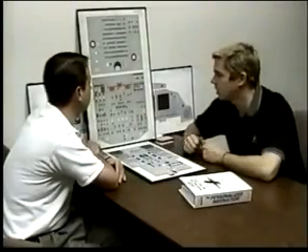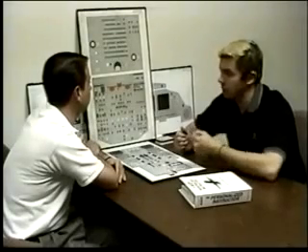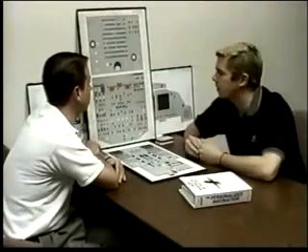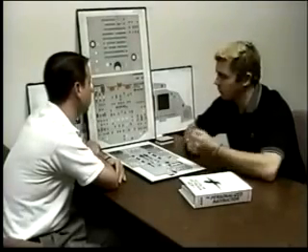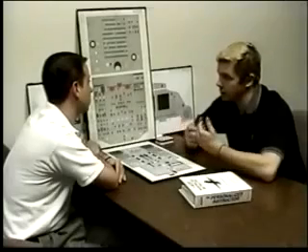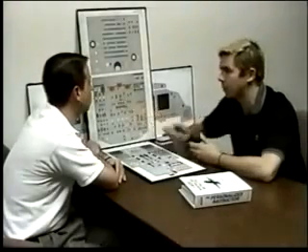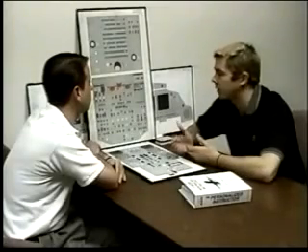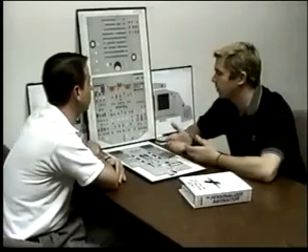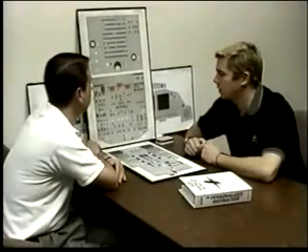So I taxi out now. As soon as I move the flap handle out of up, the slats are going to come out and the center tank pumps are going to shut off. I'll take off. When I raise the flap handle to 0, the slats are going to retract, and therefore the center tank pumps can again resume their operation. This will happen until we burn out all the fuel in the center tank. If that happens, the center tank pumps will run for 5 minutes, and then